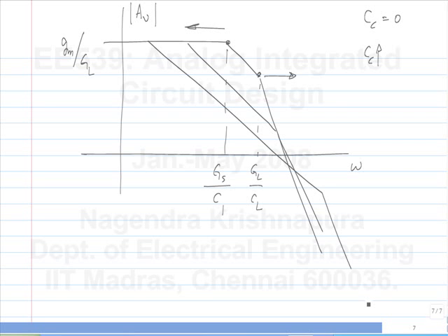Is that okay? So what use is this? This is what is used for compensation. Anyway, we'll see the details later. But this was just to give you a feel for why the results come out the way they do, and also why the CC in particular is a useful term. So by making CC larger, you can make it look like having one low frequency pole and a high frequency pole like very high.